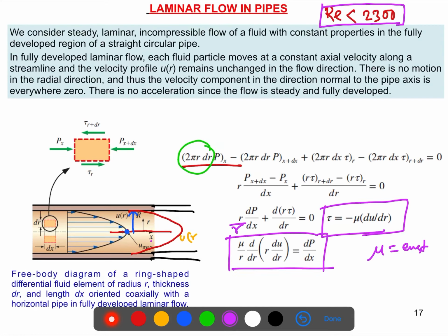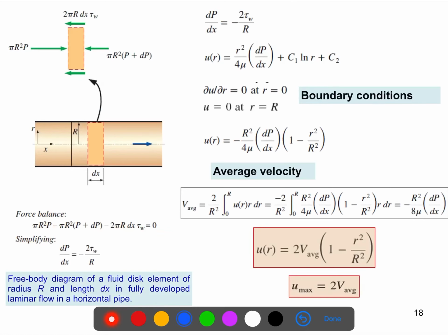If you go through the books, then you will see the detailed calculations over there, so we will get these expressions. So we have this quantity, du/dr. This is actually the rate of change of the velocity in the radial direction. It is negative in pipe flow, and so the negative sign indicates that. We can write it down like this: du/dr is equal to negative du/dy.